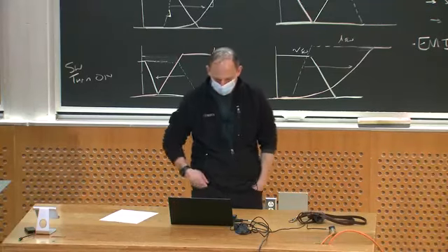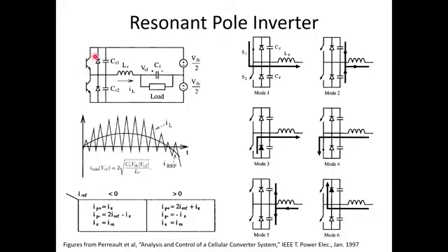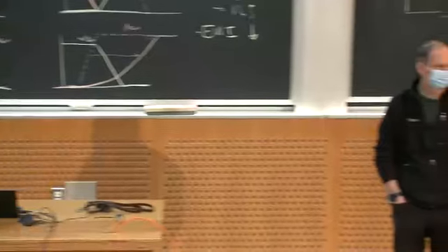And what we can see is here's my switch, and I'm showing, you know, like an IGBT or a bipolar with a diode across it, but this could be a MOSFET, okay? And each of the two MOSFETs in this bridge leg, right, this is clearly a bridge leg or half bridge, has a capacitor across it, okay? So what does that suggest to you about what kind of soft switching I'm going to be doing? Got capacitance across my devices.